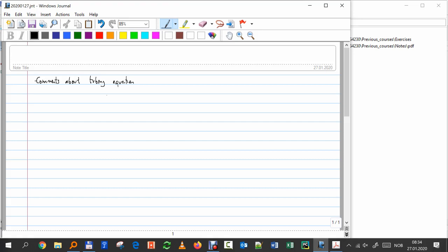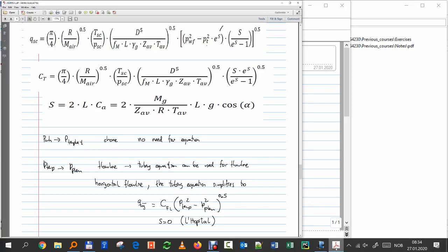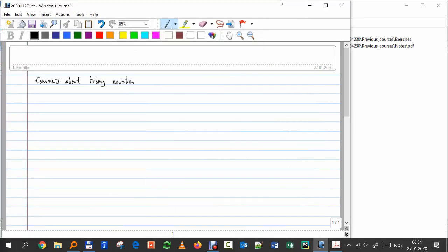So you have there, if you see on the equation, you have T average, and you have Z average. T average, if you are talking about a tubing, will be T flowing bottom hole temperature and TWH, wellhead temperature, divided by 2.